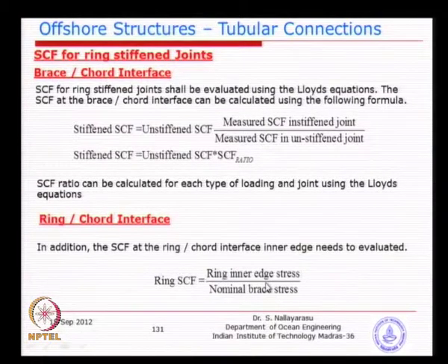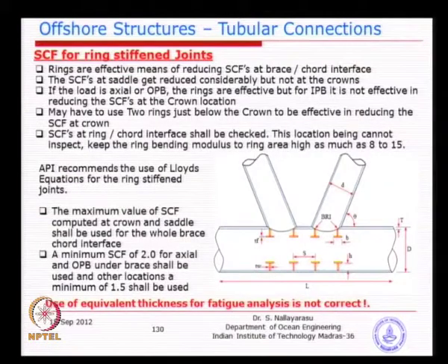but if you have forgotten to do this, probably a problem. And many times, depending on the joint configuration, whether it is a T section or a simple flat bar, the stress concentration can be different. Also you may have to look at the stress concentration factor at the interface between the flange and the web at this junction, which sometimes can also be very large.